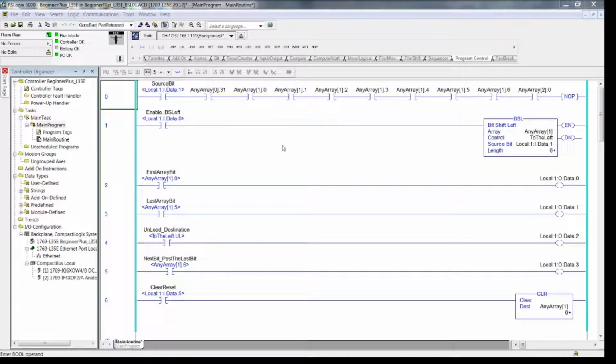We tend to work with 1s because it's easier to see the shifting, even though the 0s shift equally as well as the 1s. I then had you turn on the source bit and leave it on. First I had you test it, then I had you just leave it on. So right now, if we were to execute a bit shift left, a value of 1 is poised to go into the first position.